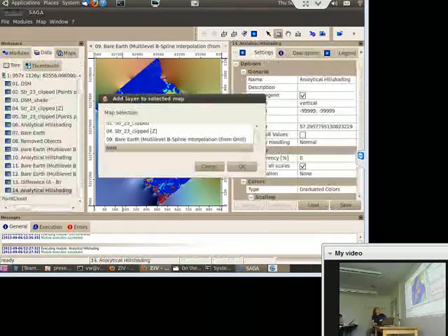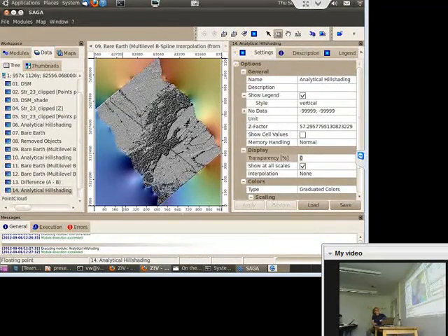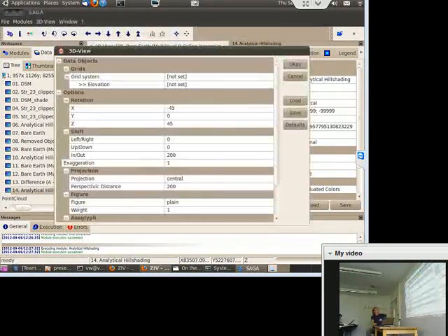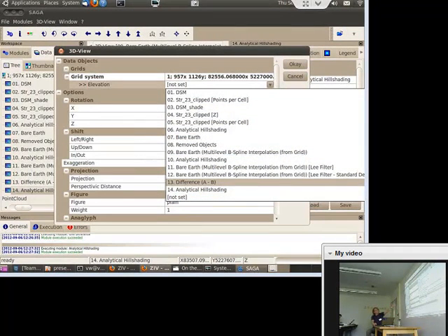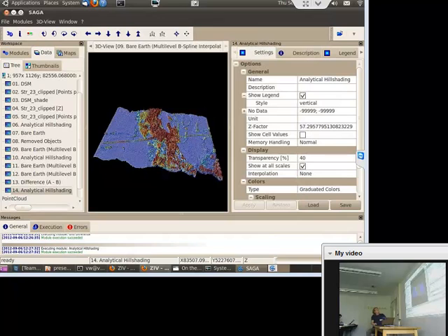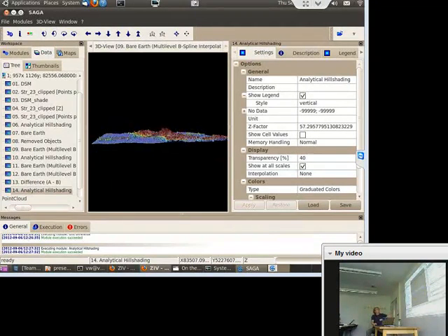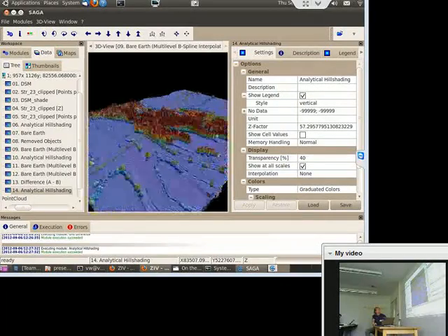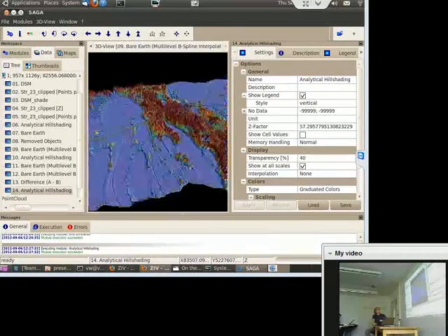So, and overlay 40%. And once you look at this one with the raster 3D viewer, you see it's all plain. You must select as elevation the difference grid, the NDSM, and increase the resolution to 1000, for example. And then you see we have a completely plain model where each cell just represents the height of each object on top of the Earth surface. So that will be the tree heights or something? Yeah, this is tree heights, for example.